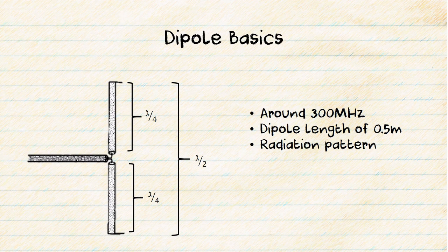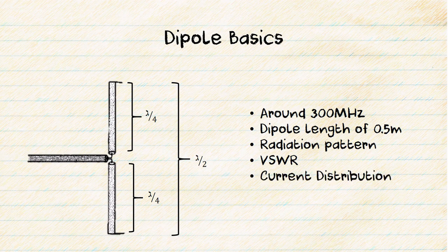I'll be showing you how to explore the radiation pattern of different antennas, how to see the VSWR of your simulated antenna, and see the current distribution, and obviously I'm just going to show that the simulation is working correctly. I'm going to show you on the VSWR how the characteristic impedance of our half-wave dipole is the standard 73 plus 43j ohms.